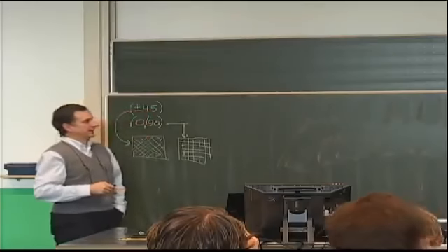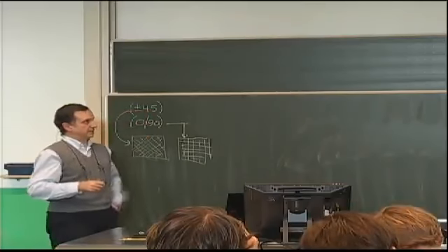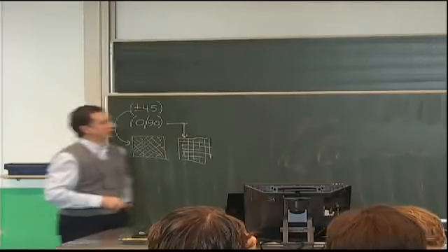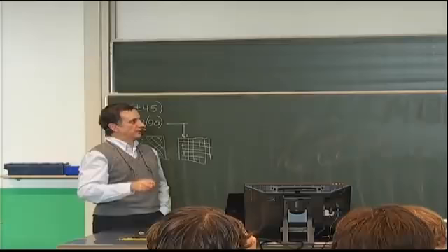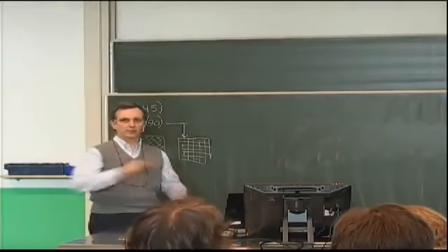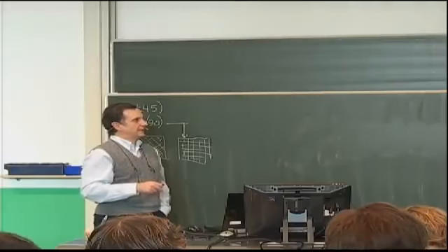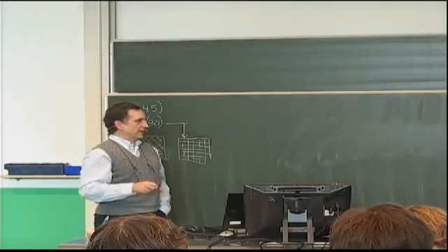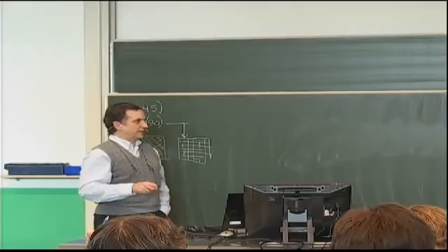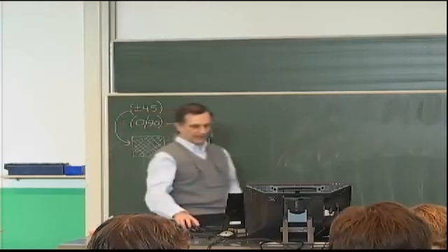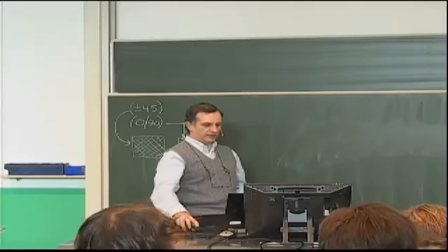design problem. Another case that we will try to solve exactly involves a plate with a point force, transverse or vertical point force, which can be anywhere acting on this plate. We assume again a symmetric layup, so the B matrix is 0. We assume that D16 and D26 is 0. And why do we bother?